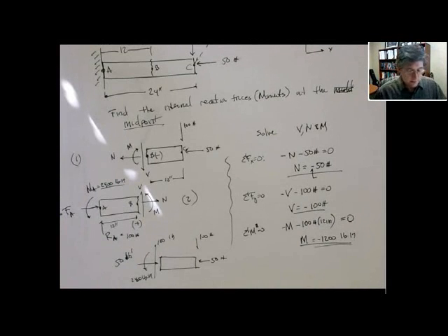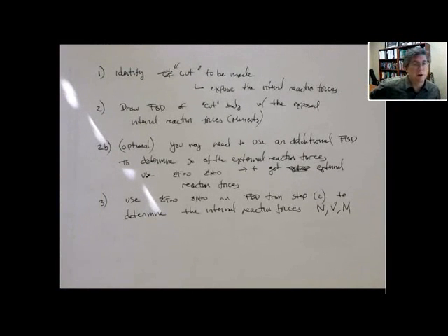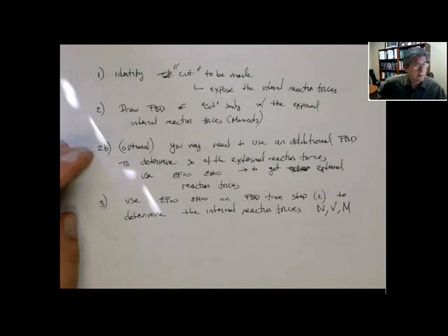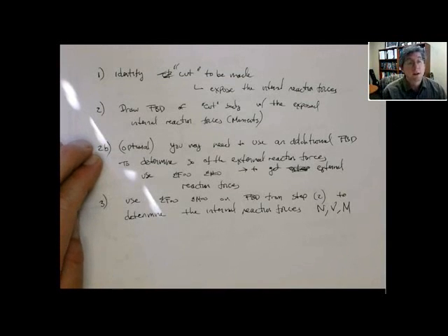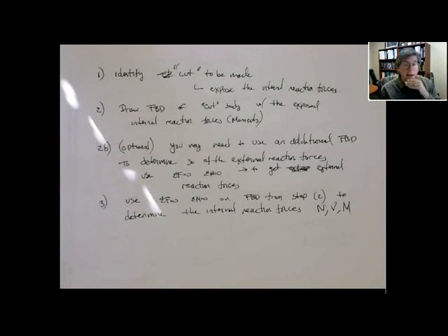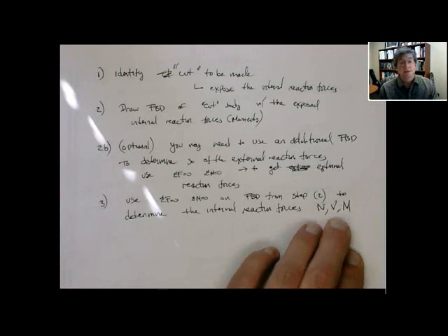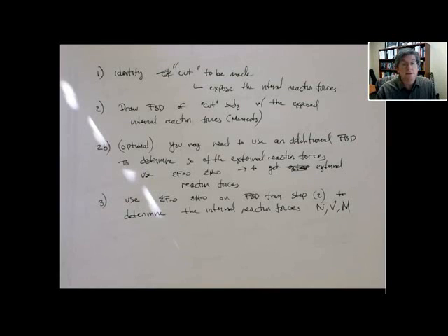So these are the steps for when you get these problems where we have to determine the internal reaction forces. Don't forget, sometimes you might have to use multiple free body diagrams to determine some other forces, so that you get all the forces known for your free body diagram that exposes A. And again, we're going to use these in subsequent chapters to compute stresses. That's what we're going to use to size or to design components.